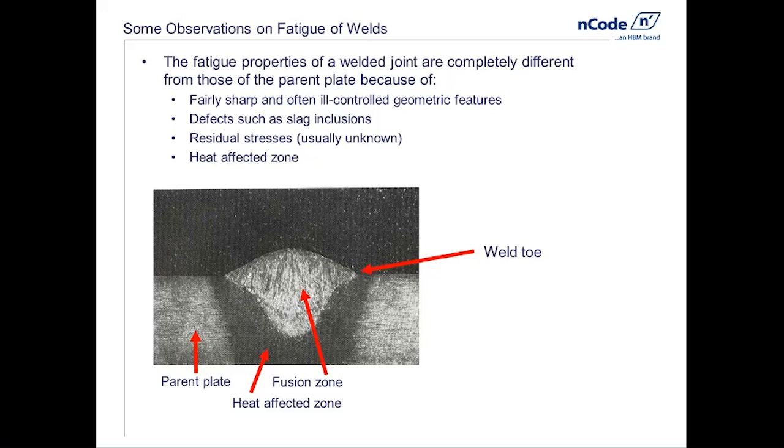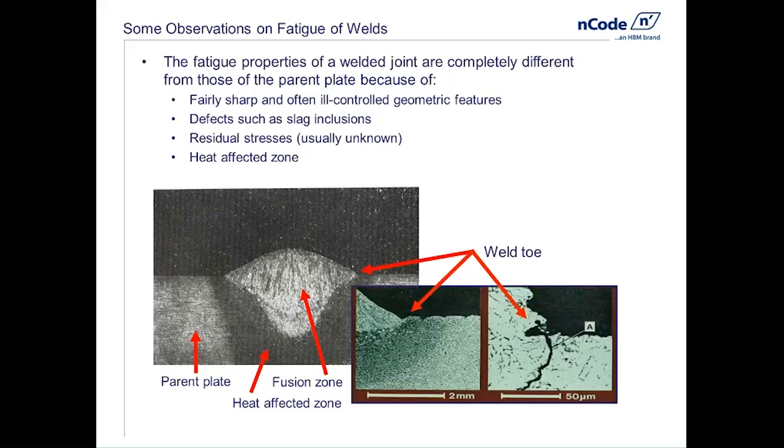When we're looking at welds, that becomes not practical in most cases because we now have a geometry that is very difficult to describe in a finite element model. We have aspects of the weld such as the deposited metal from the weld, a heat affected zone around that has changed the base metal material properties. We have residual stresses, many times very large and unknown. And again, looking at the details of the geometry, we're looking at things that would be virtually impossible to build into an FE model.